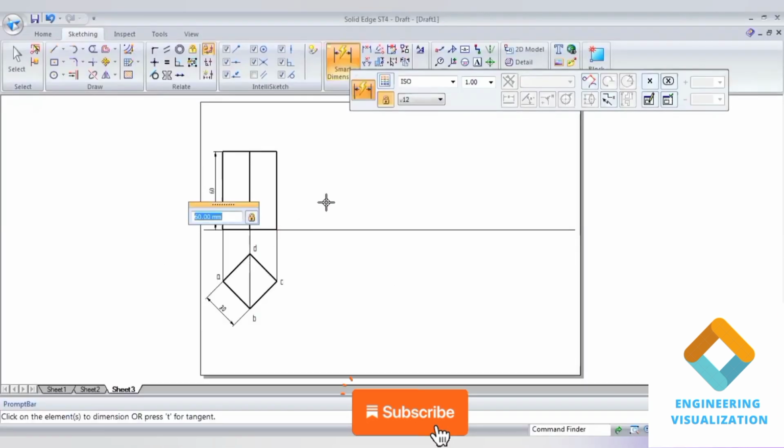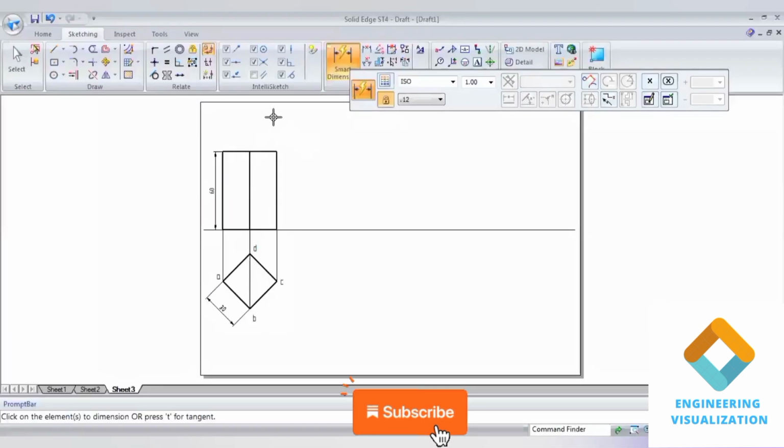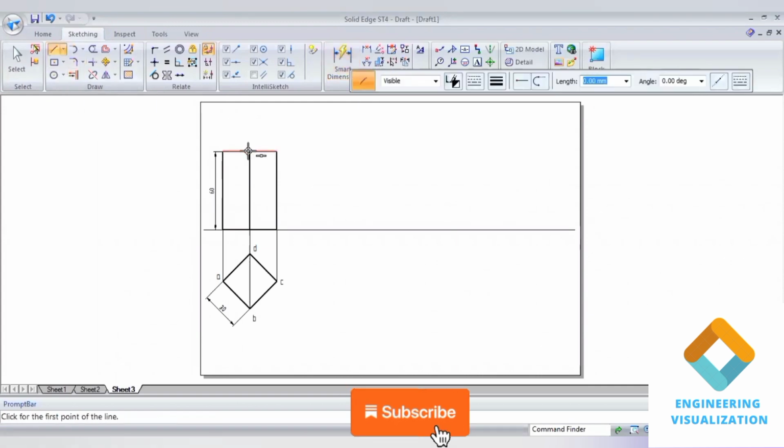Now we have to draw the section plane which is at a height of 50 mm from the base, and it is exactly cutting the axis at a height of 50. So for that I'll be drawing a 50 mm line from the base, exactly from the center, on the axis. So go to line. From the bottom I'm going to draw, that will be convenient.